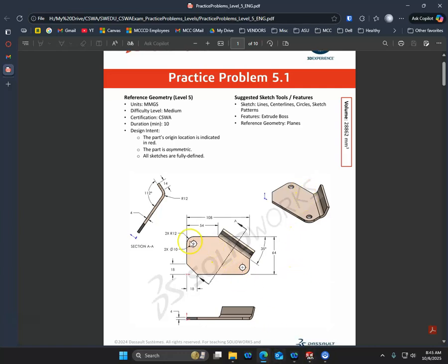The other one was the 2010 version switched over to the primary, secondary, and tertiary, and it's just a matter of setting up the selections. So as you select, it gives you options as to what geometry you can create. The other thing that wasn't in that list is if you select an edge, select I believe a line, but definitely if you select an edge and go into sketch, whichever endpoint of the edge that you're closest to, a plane will show up at that, basically tangent to that point, tangent to that curve.